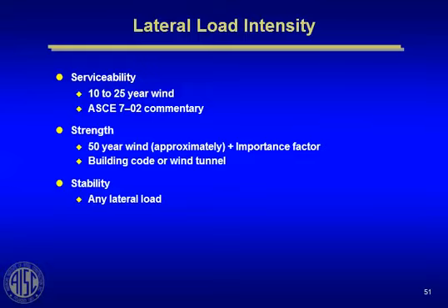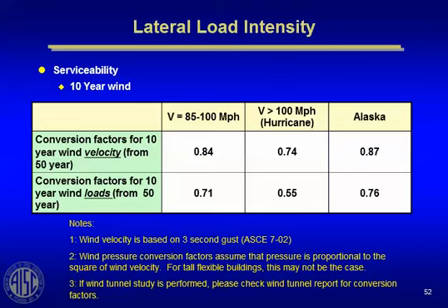How do I get the 10-year storm? If I'm going to use a 10-year storm or a 5-year storm or a 75-year storm, how do I get that? Well, guess what? ASCE 7, Chapter 6 in the commentary has a little table. It shows you how to convert from a 50-year event, which is what's mapped, to a 10-year event or a 25-year event or whatever event you want.